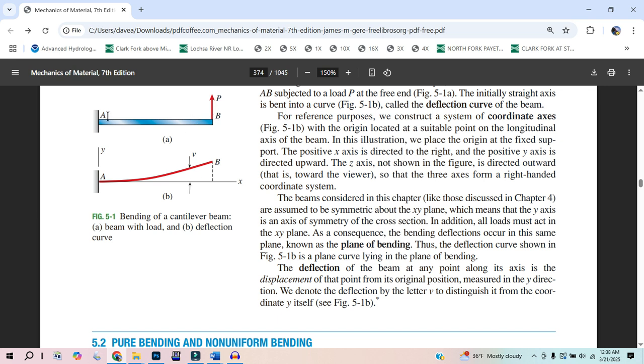And so in this scenario, it should work out. Let's try it out. If my shear force is going to be upward on this face, that's going to be negative. So let's draw the shear force in. Here's my shear force diagram. It's going to be negative P all the way over to this load and then up. So at the reaction, I'm going to go down negative P, over, and then up P. So then what is my moment? My moment should be negative.